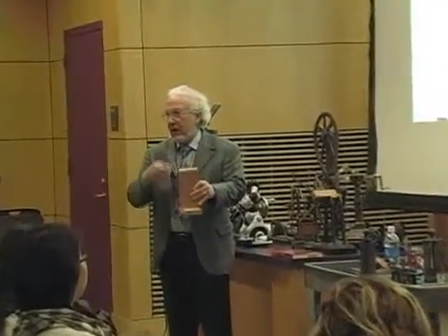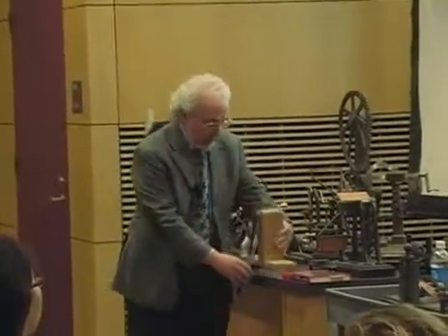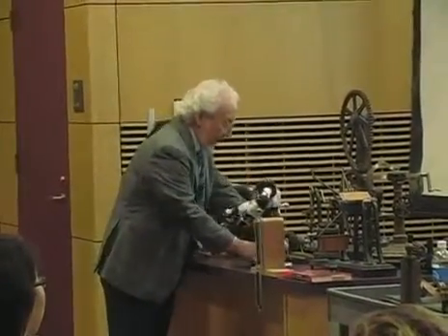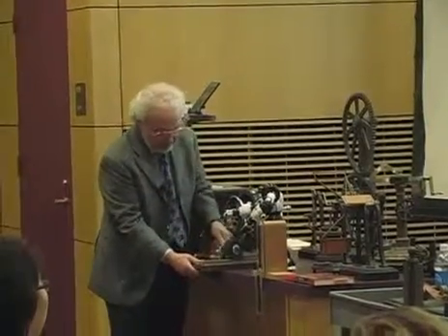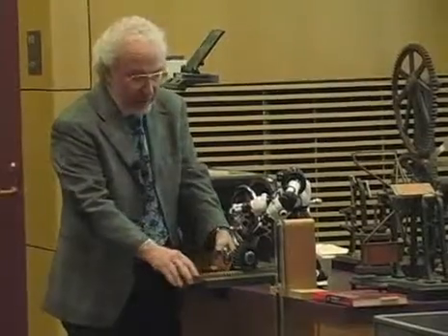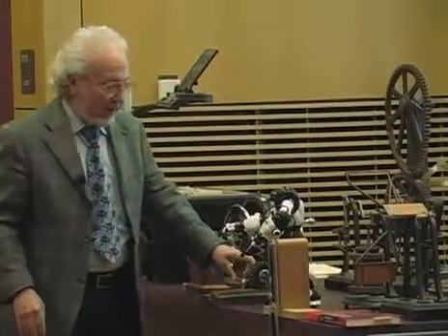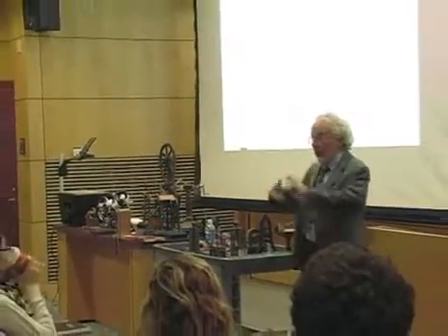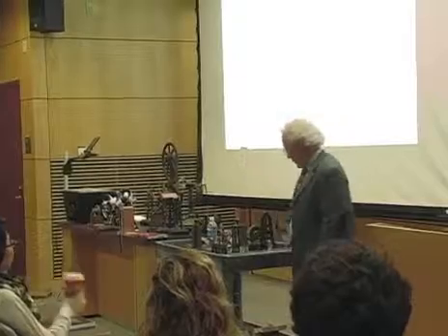So we can have things like rotary motion. We can also have joints that have sliding motion. So we have this rack and pinion here, where this rack is only sliding. We call that a prismatic joint. We also have joints which involve a screw, which involves rotation as well as translation.